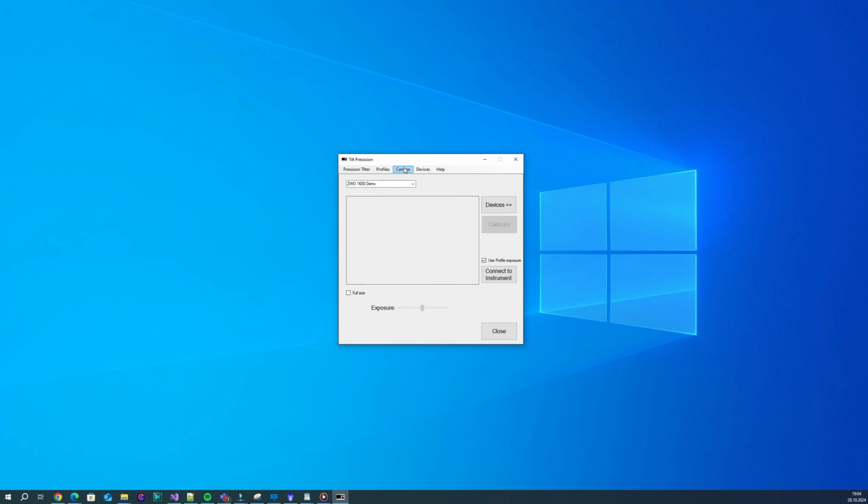The application has now to be connected to the instrument. First, select Instrument Camera in the Camera menu. Then, since this is the first time calibration on this setup, uncheck the Use Profile Exposure so that ideal conditions are calculated. Finally, press the Connect button.